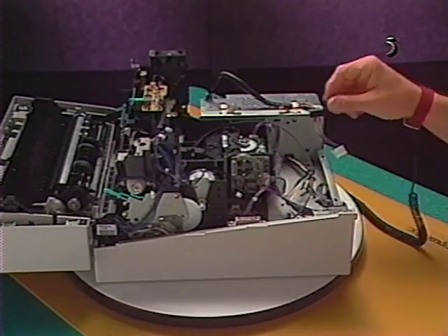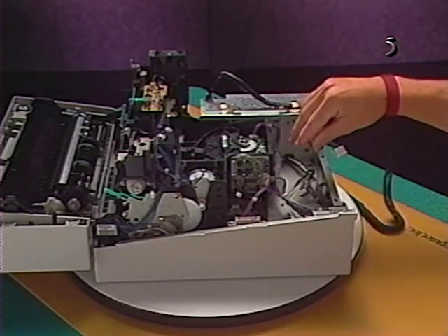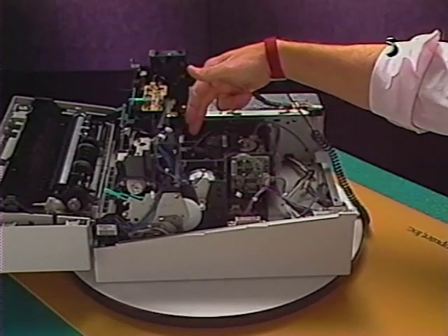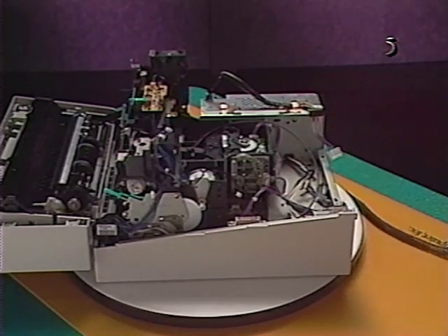Located in the front of the lens assembly is the optic fiber cable. It carries the laser light signal reflected from the lens to the DC controller of the PCB to indicate that the beam is about to start a new scan.